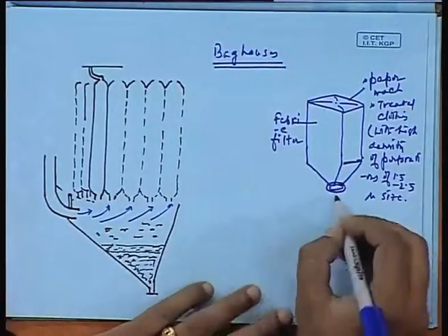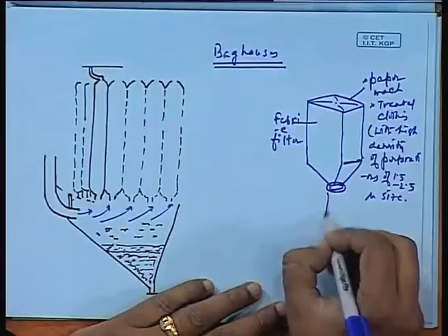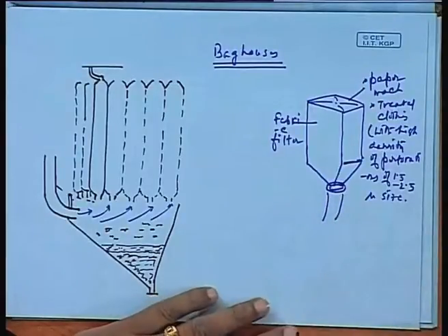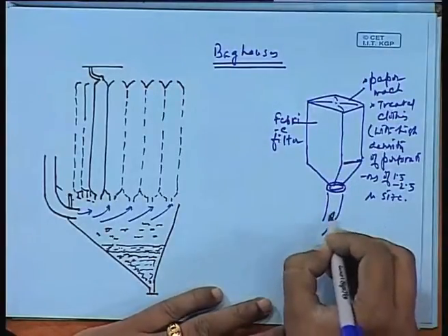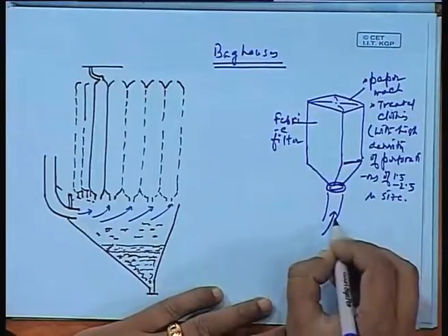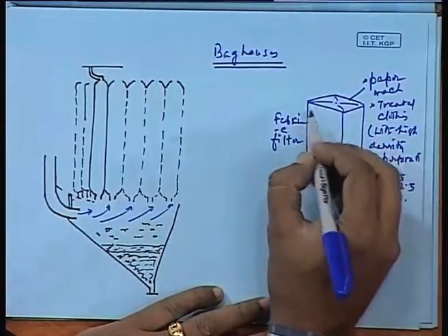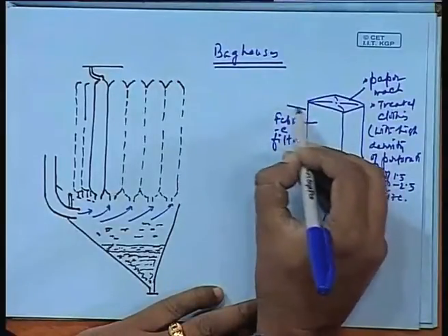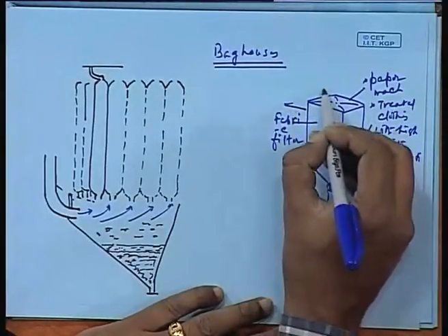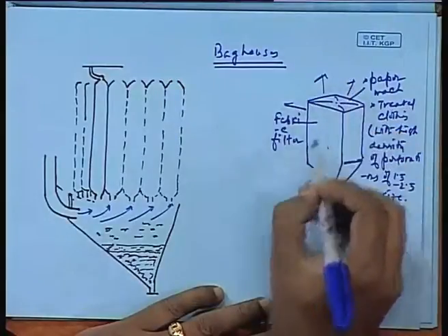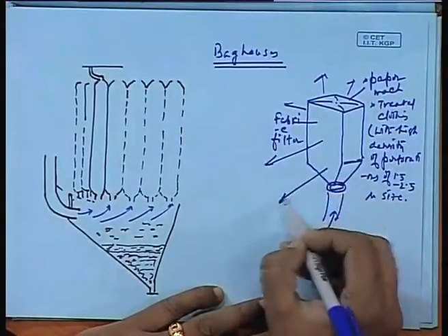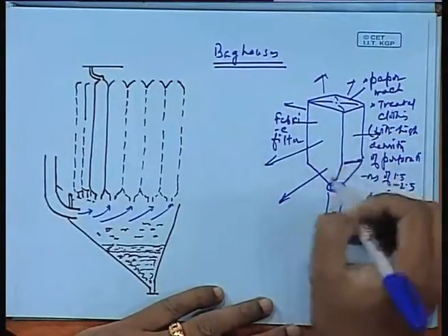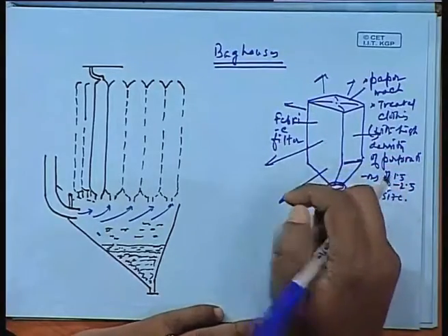So what is happening here is, as in a vacuum cleaner, the air enters and is sucked through. The dusted air passes out through the perforations, and the particulates are arrested on the bag itself.